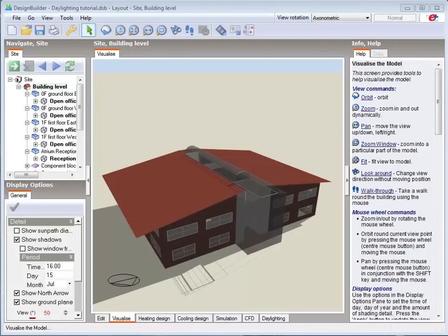Designbuilder includes all the model data required for daylighting calculations. When you click on the Daylighting tab, this data is passed to Radiance, which uses a ray tracing calculation method to calculate the distribution of illuminance in the working plane. The model data passed to Radiance includes the visible reflectance of surfaces, site ground reflectance, window glazing transmittance, and detailed geometry including local and component block shading devices.